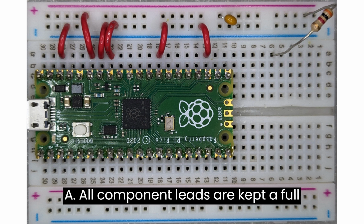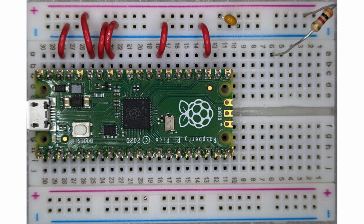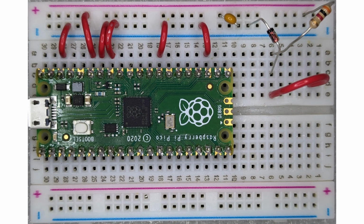All component leads are kept a full length. Trim the ends if there is adhesive from a tape strip. Connect the diode from breadboard bus 6C to the negative bus. Add a 2-inch jumper wire from breadboard bus 6E to bus 2D.